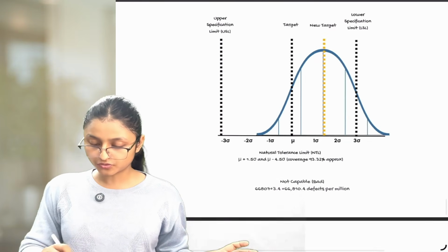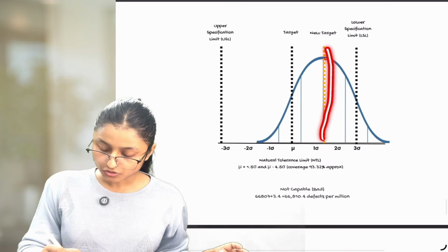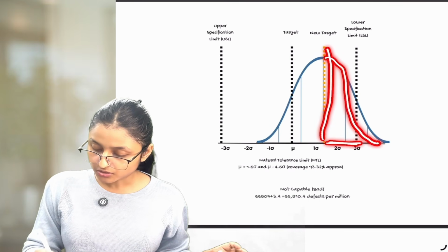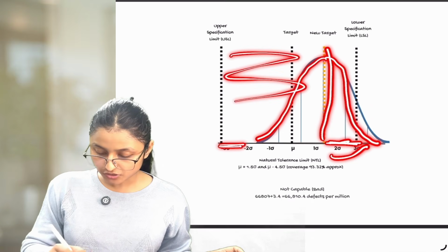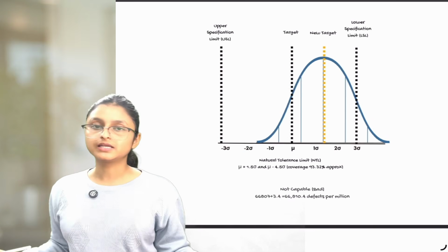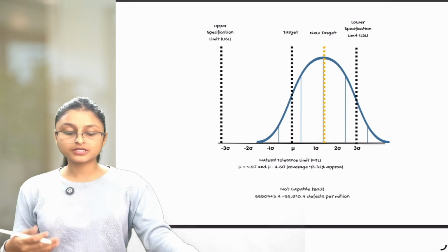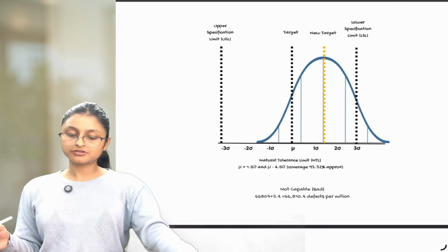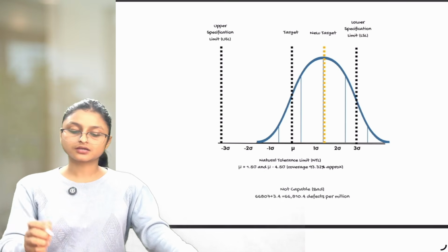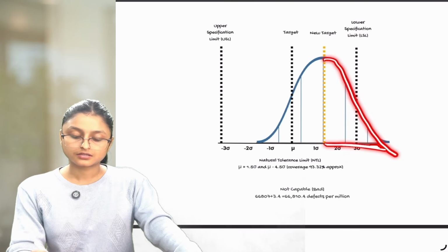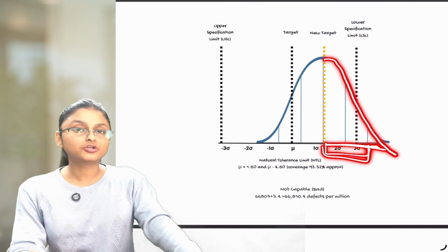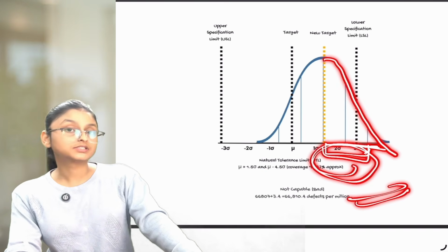Similarly here, our normal distribution has come a lot nearer to this area but is very far from here. So chances of getting defects here become very small. That is why, whenever we have this 1.5 standard deviation shift, we only check the defects near our mu. The line which is near to mu, we check the defects of this side only.